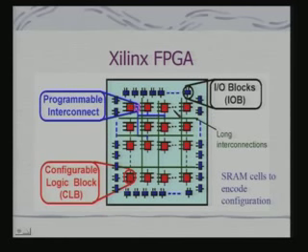That means, using these blocks, you have the ability to synthesize any kind of circuit. In fact, SRAM cells are used to encode the configuration, which essentially means that if I change the SRAM data, I can get another configuration for this FPGA block.